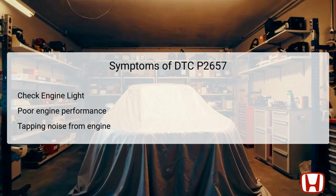Additionally, drivers may experience poor engine performance, including hesitation, reduced power, or inefficient fuel consumption due to impaired valve timing control. Another potential symptom is a tapping noise from the engine, often caused by improper valve operation linked to oil pressure irregularities. These symptoms highlight the importance of addressing the P2657 code to prevent further engine damage and ensure optimal performance.